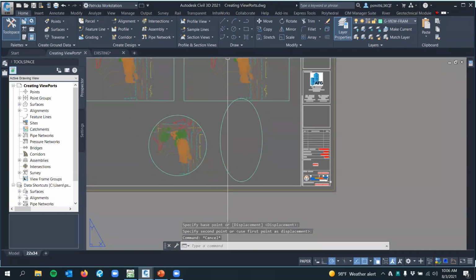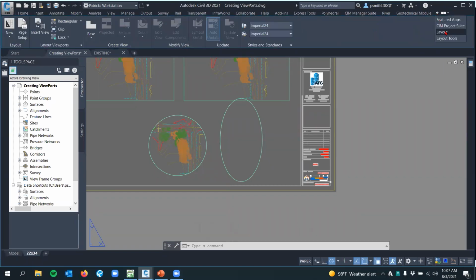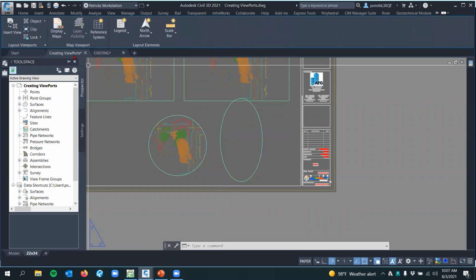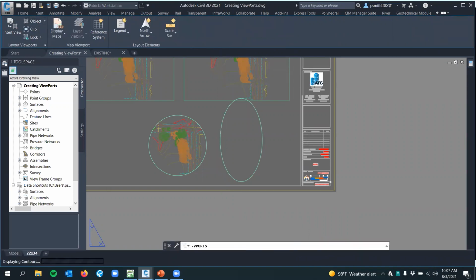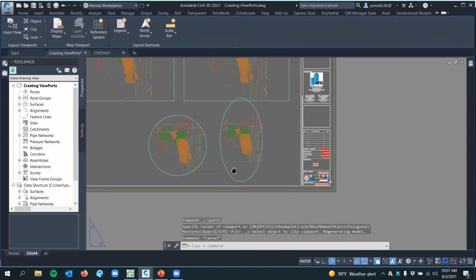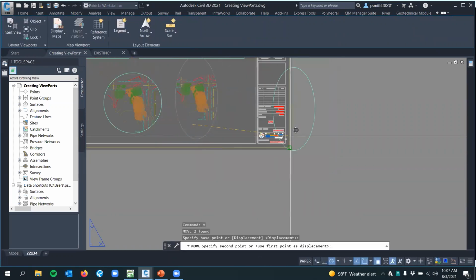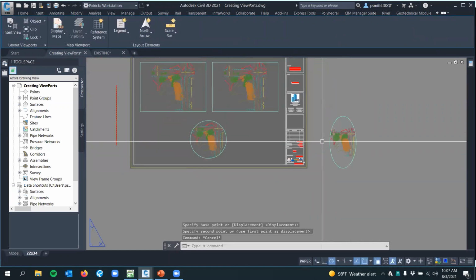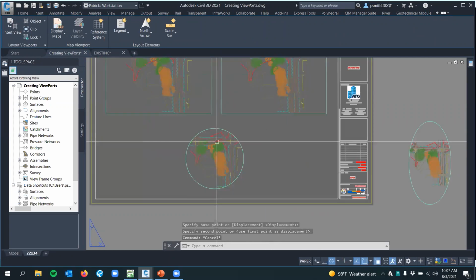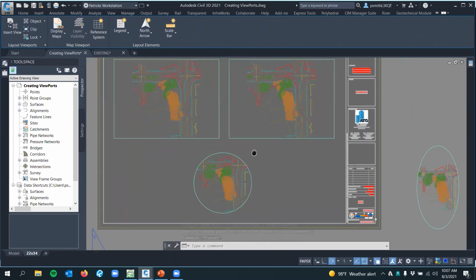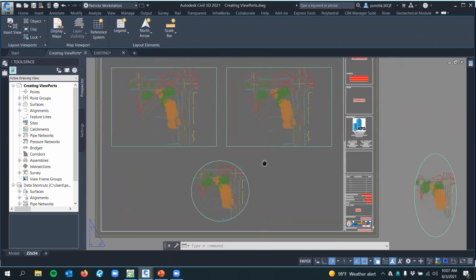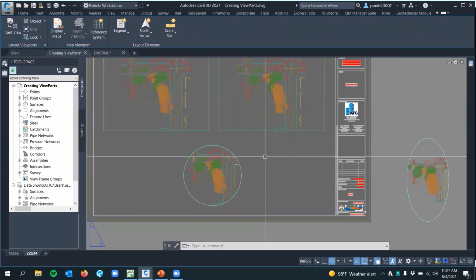All right, go back to your layout tools. Layout and Layout Tools are just about the same thing. You get the same panel here, whether you click on Layout or Layout Tools. If you're wondering that. Oval shapes, there you go. Some of this is very basic, but a lot of people don't really know that function right there. Creating viewports from the objects that you create.